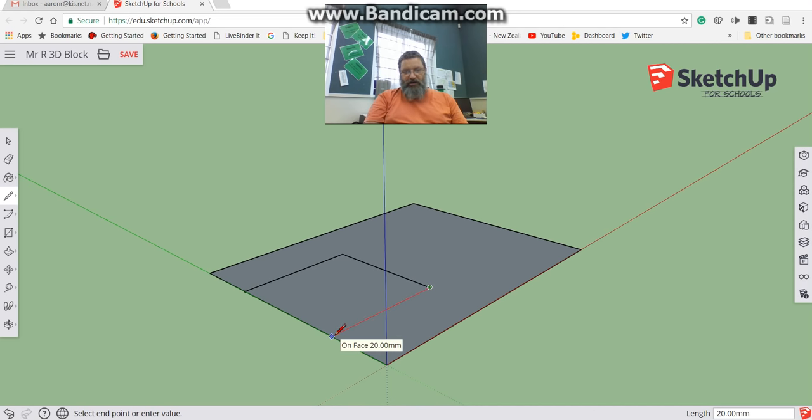Now I can go back to that guide point, to where it says guide point, and click on that, or I can just move my pencil around until it's red and type 20 and enter. Oopsie. I did something wrong, so I'm going to go Alt backspace to undo what I did.